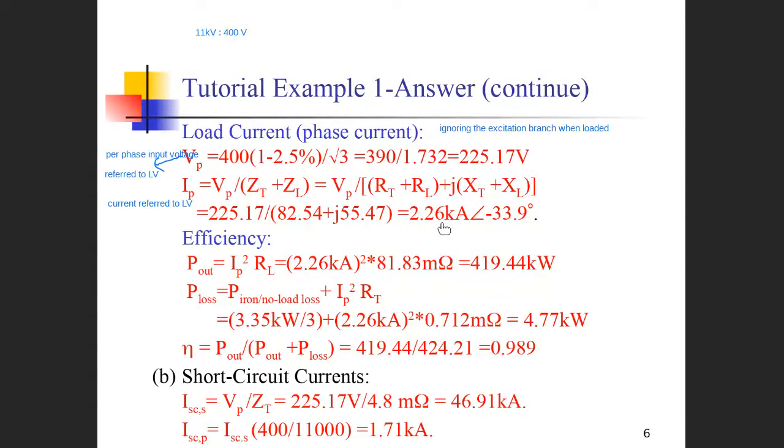You can find out the loading currents. This is the loading current, the actual current. So this current is slightly smaller than the rating current. Okay, so this is the loading current. And you also found that the output current lags the output voltage by an angle. This angle is a little bit larger than the angle of the loading itself, because the internal impedance of the transformer contributed to this impedance angle. Okay, that's the meaning of it.